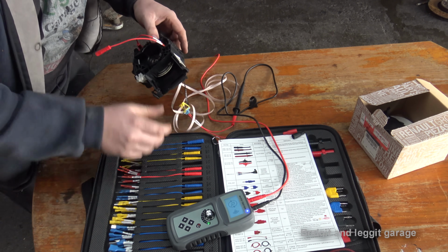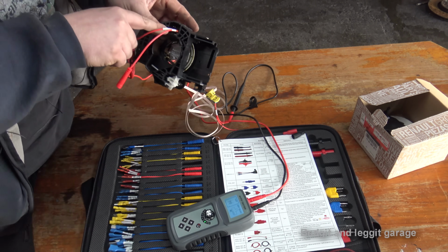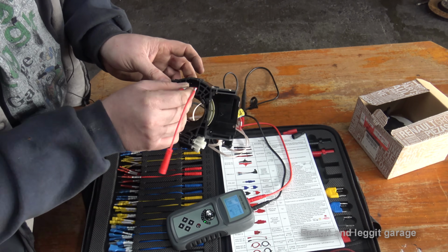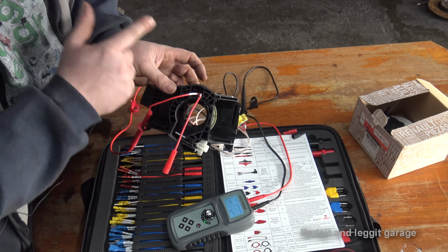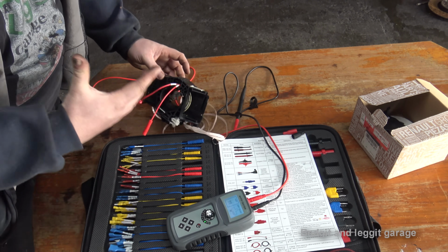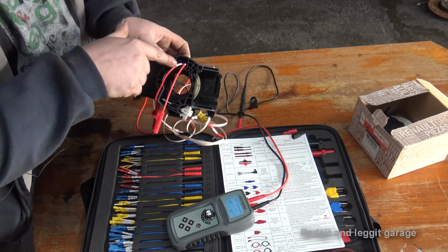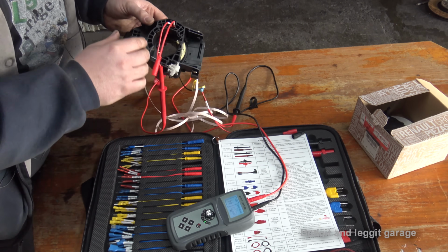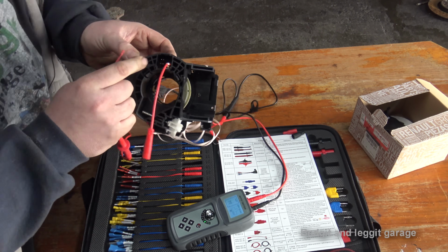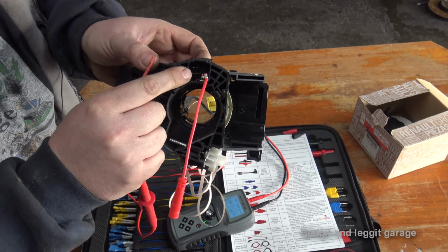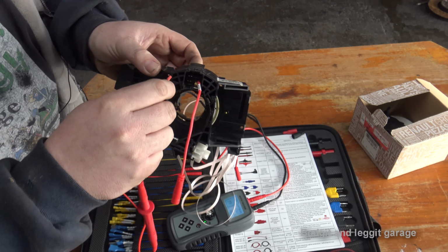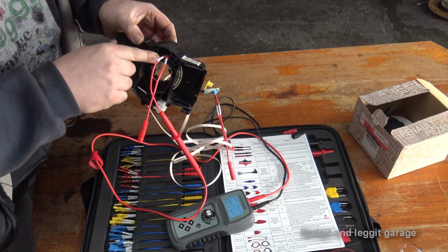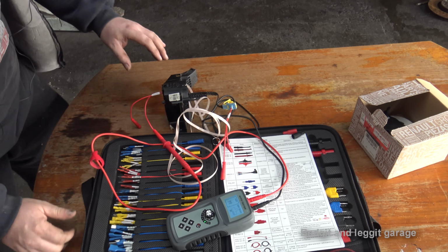Somewhere. Now what you do have to do, let me just turn it off, when you're testing an airbag, you see these two little pins. When you pull out the connection, the pins pull out, and it essentially makes it safe. So you have to make sure those pins are pushed back. I've shown that in my other video a lot clearer. But I don't know if you can see, the camera's going to show that locking pin there. When I push that down, it separates it, so it means I can test it. If you're trying to test it with that pin engaged, you're going to get completely false readings.